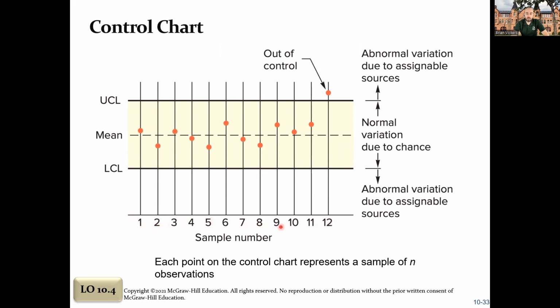You've averaged out the samples from that day. So sample number 1, you might have maybe 5 observations that day, and then you average out to get your sample for the results. Then you plot it compared to the mean. So you've got the normal, what you expect it to be, and then where that result is, it is plotted out, and you can see all these dots lie within the upper and lower control limit.